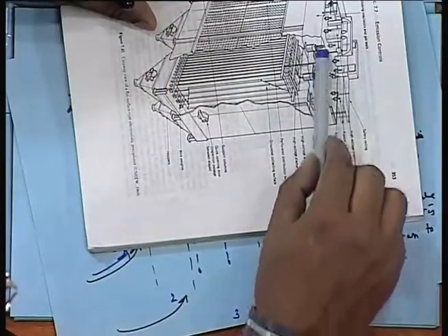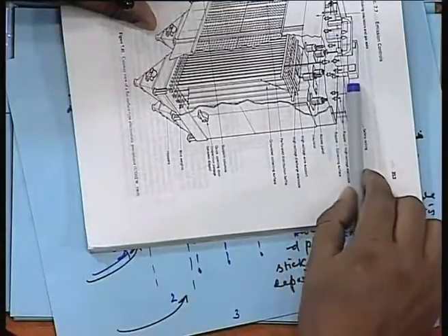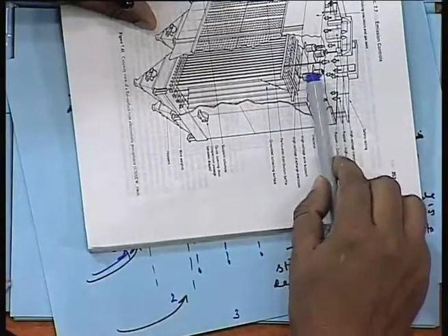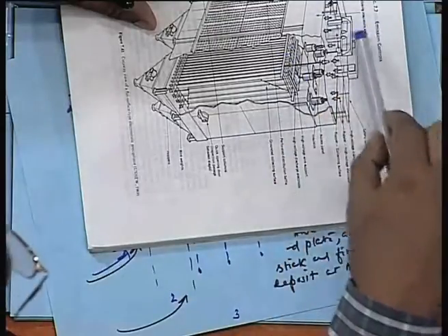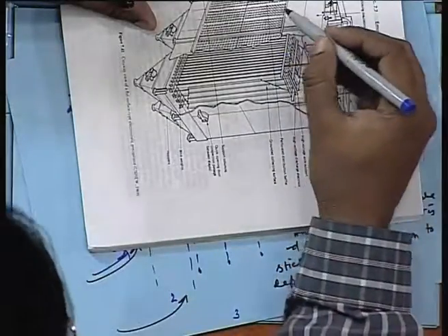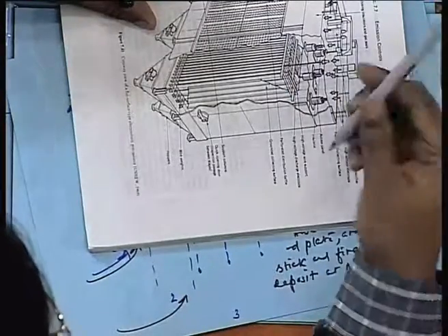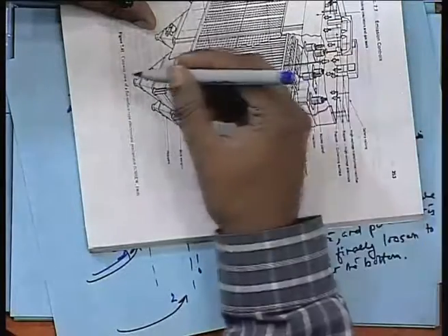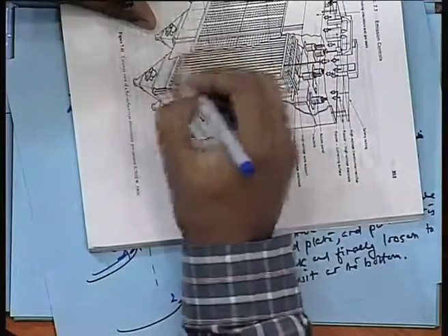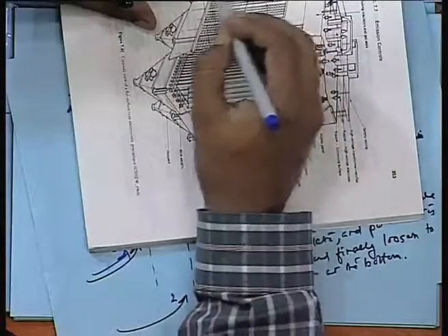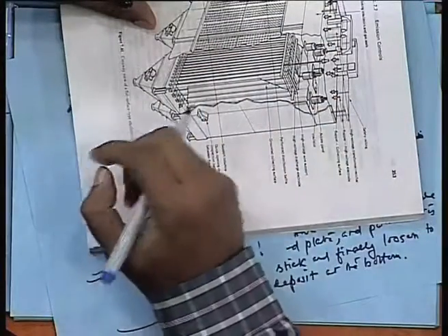This is where the negative voltage would be generated. Through these outer surfaces, the gases would be coming out, and the particulates would settle at the bottom, or remain stuck to the grounded collector plates. This is mostly how it looks.